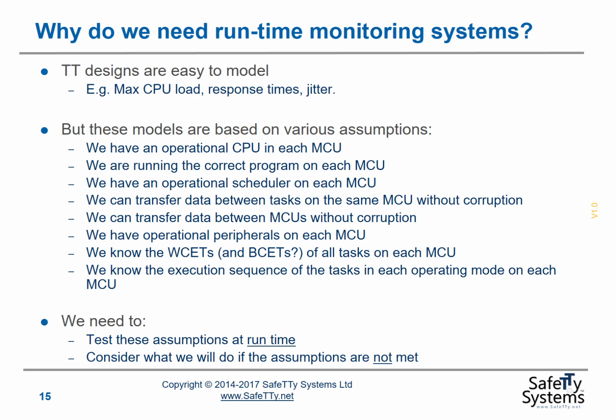We then went on to consider in some detail the need for runtime monitoring systems. So once we've got our model, we have to accept this model is based on various assumptions. We have an operational CPU in each microcontroller. We can transfer data between microcontrollers without corruption, for example. And we discussed the fact that we need to test these assumptions at runtime, and we need to consider what we will do if the assumptions are not met at runtime.